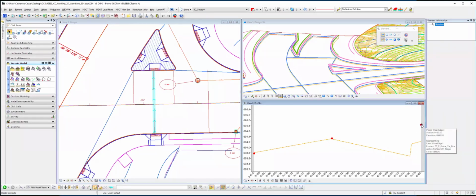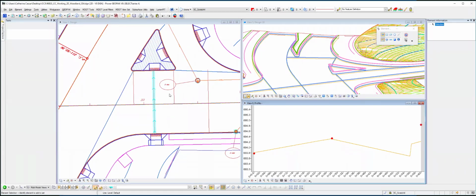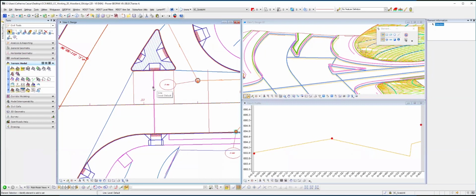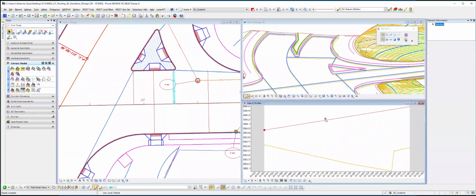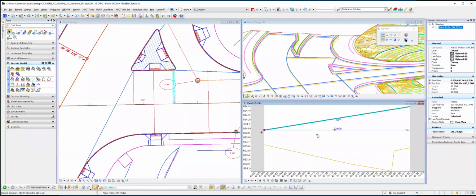I just see those intersections. Those are just MicroStation lines then? These are MicroStation lines, yeah. Like I said, I use these sometimes, but I typically will not add them to the model. They're used as my controls when I use them, but I would recommend that you actually use smart lines as opposed to MicroStation lines. I ran into some hiccups. If I was adding these to surfaces, actually adding them to the surface, I would make smart lines. But because I was just using them for checks and controls, I did not in this case. But I did run into some trouble down the line.